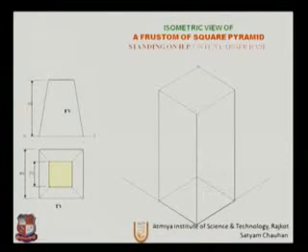So this will be the cube with the height of 60 and base 40. See, the overall dimensions need to be observed first, and then the overall planes are required to produce, and then we will start to draw the isometric in this box.